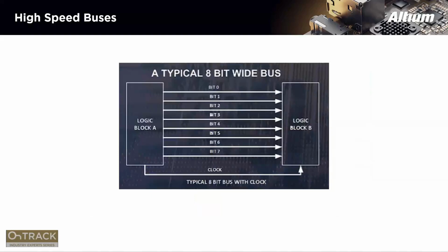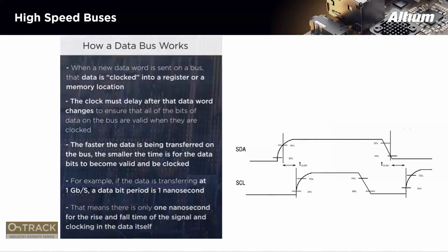If we have a more detailed view, for example an 8-bit data bus, we see the 8 data lines on the clock. That means the system is synchronized. Now the number of data lines can vary. In CPU systems today we see 64 bits of data, whereas systems from early times had 8 data bits. Due to the complexity in routing 64 lines and managing their length, and the fact that designs get smaller, we see a trend in moving towards serial systems rather than parallel systems.